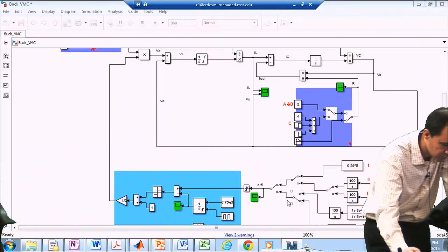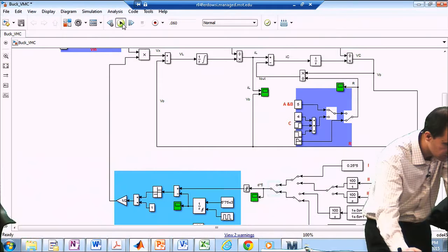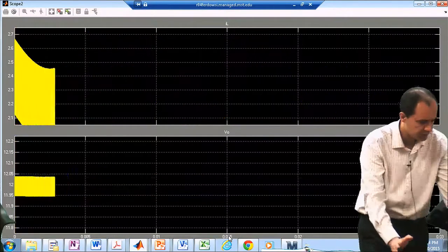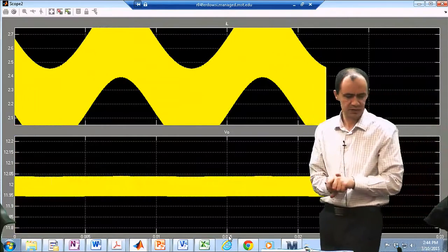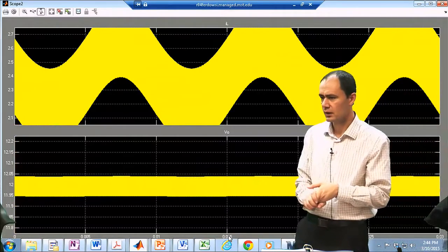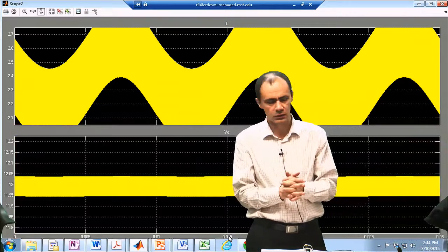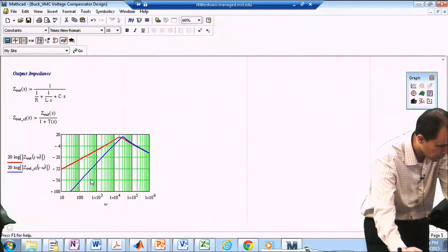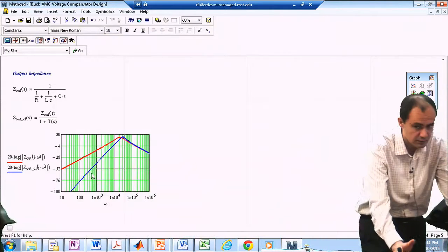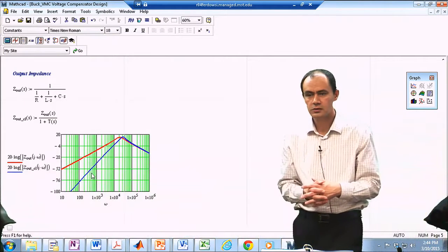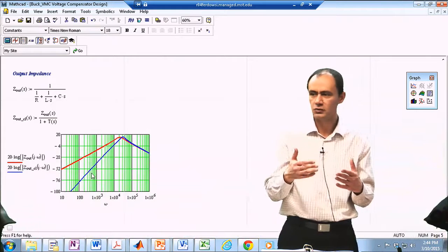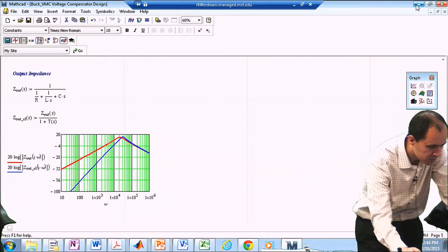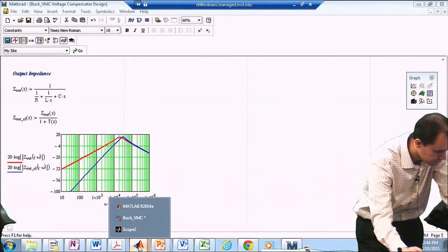Now let's close the loop with the giant transfer function. So it got a little bit better. Even at this scale, you don't even see the variations of the load in the output voltage. So you're doing a good job in terms of load regulation. Again, the explanation is I'm even providing more negativity in my closed loop output impedance, so it's less sensitive to the variations in the load. What about bandwidth? Let's take a look at the bandwidth example.